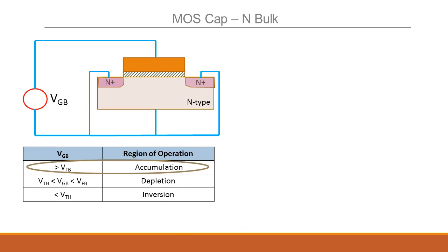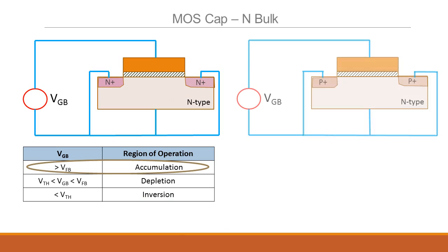How do you fix that? Right. So this kind of cap we'll use only in the accumulation region, because in the depletion and inversion regions, the depletion region cap is small. In the inversion region, the connection to the backplate is bad. That's what we discussed right now. But how do you fix that?